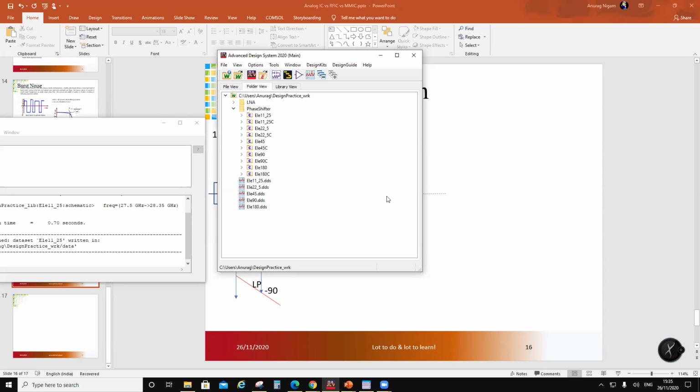If I want, I can. It is going to be slightly more difficult. You have to tolerate more mismatch, right? But what you can do is just use two lines which have a differential of 5.625. That would be good enough if you want another bit. You do not have to design band pass and other low pass, high pass elements. That's what my opinion is.